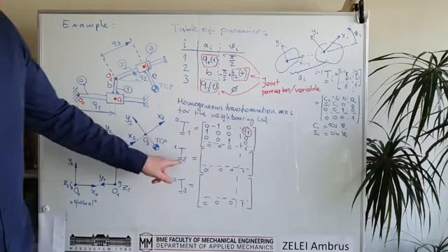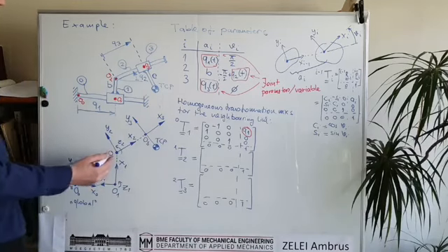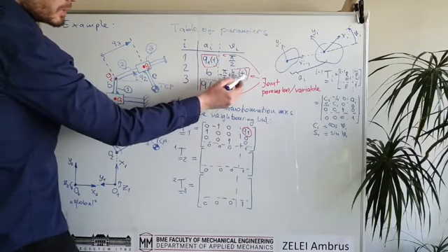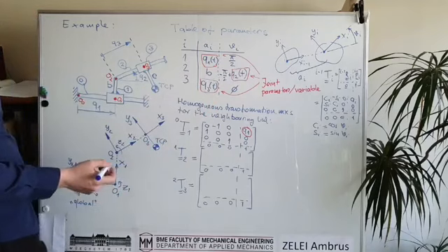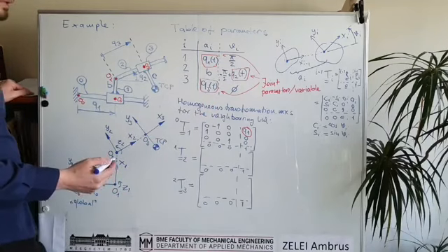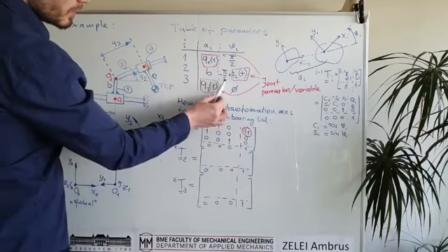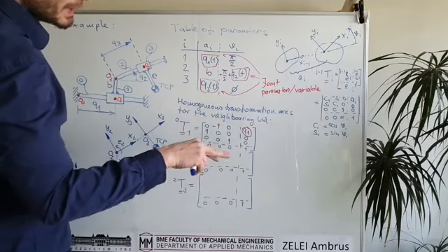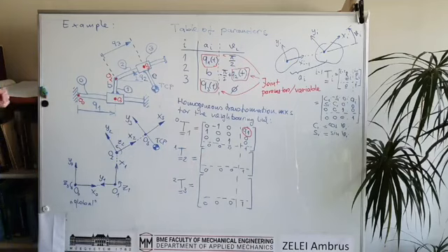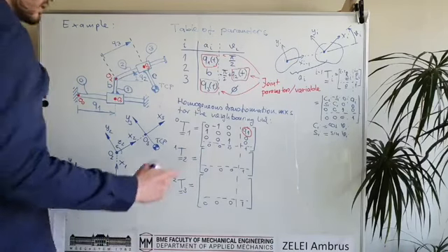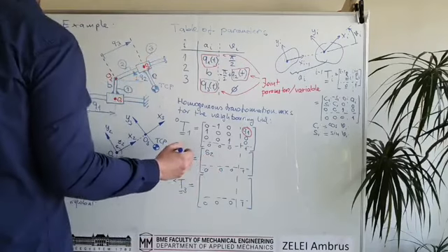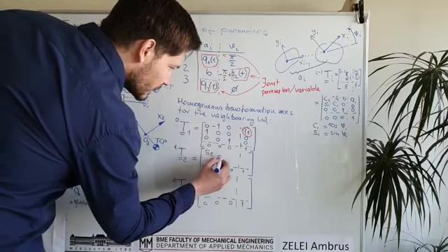And then in the second, again we have some rotation, which is q2 minus 90 degrees. Because of this, if you shift the angle by 90 degrees, then cosine will be sine and sine will be cosine. So finally it will be sine q2 and sine q2.